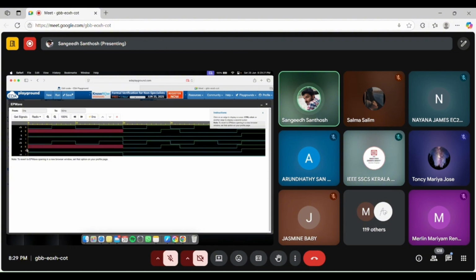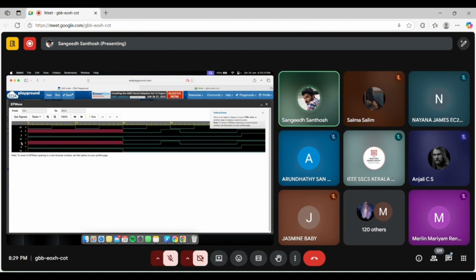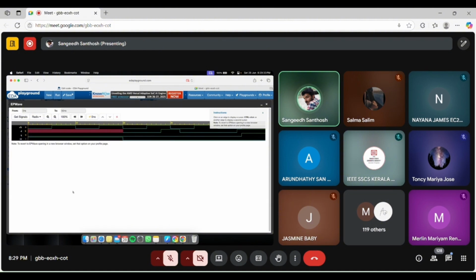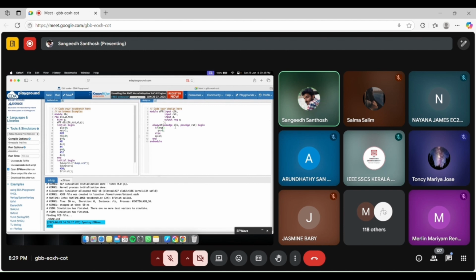So without depending on the clock, whenever reset becomes high, our Q turns into 0. Right? So this is asynchronous reset. The difference between asynchronous and synchronous, you can directly tell from the sensitivity list. Whenever clock and reset are both mentioned in the sensitivity list, we can say that this is asynchronous reset. Whenever only clock is mentioned and the reset condition is inside, you can say that is synchronous reset. Understood?